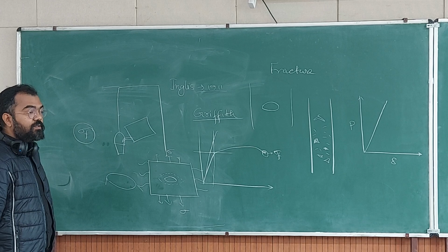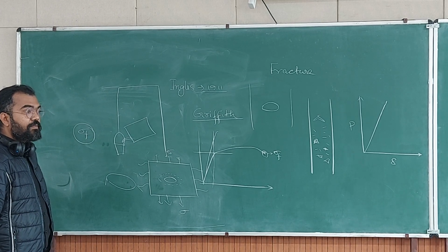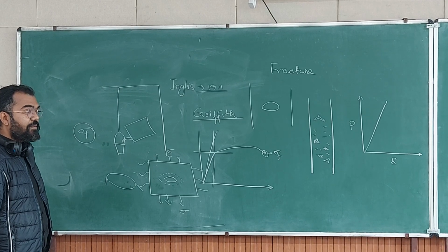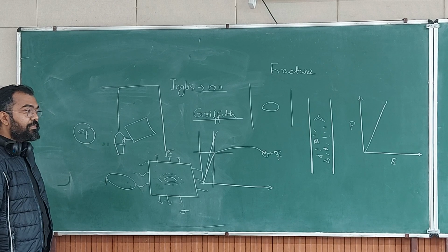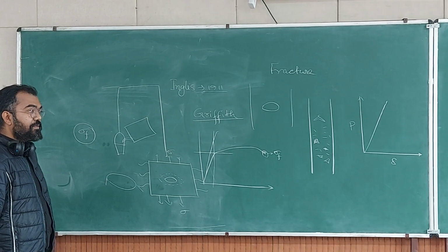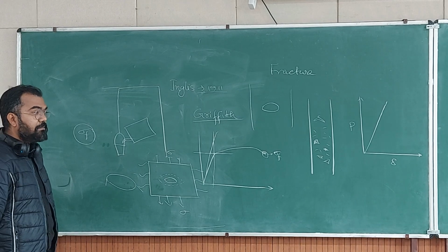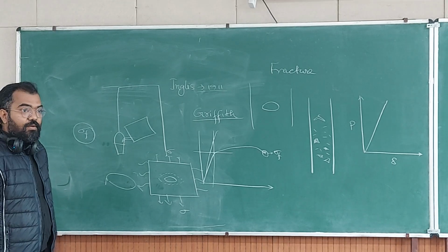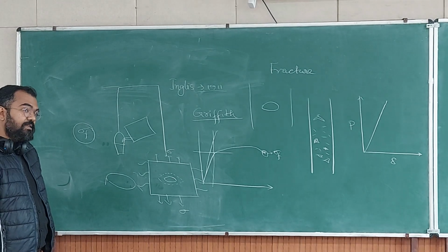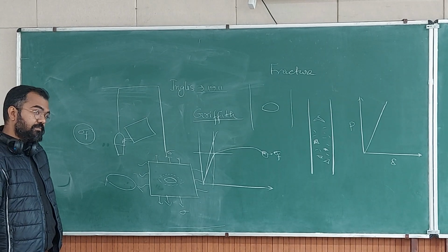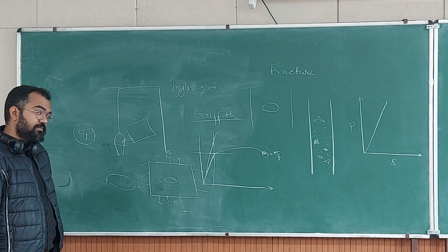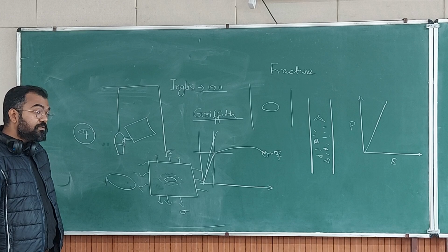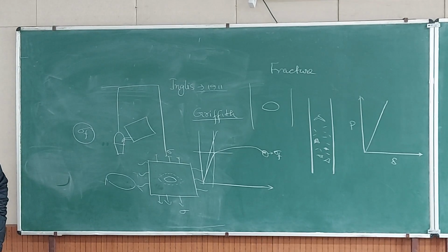That is fine. So elastic strain energy will decrease, why? Because surface energy is increasing. Why will surface energy increase? Because the surface area is increasing. Surface area is increasing for this hole. Okay, so energy is conserved, do you understand? So there is an additional surface. Crack, there are two surfaces. Additional surface is there. So total surface energy is increasing.